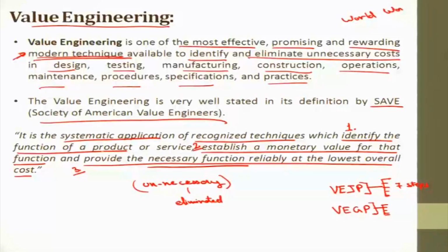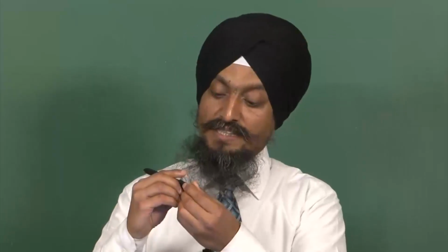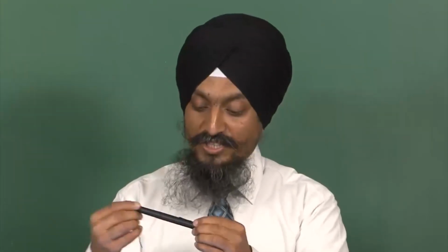The function of this body is to make grip. We take the anthropometric dimensions of the hand. A human hand can hold from maybe 7 to 25 millimeters. It depends upon the precision that we require. The blackboard markers are quite broader because the precision is less, so the size is larger. For the pens that are used to write precisely, for which we want good handwriting on the paper, the size is from 7 to 20. This is the function of the body.